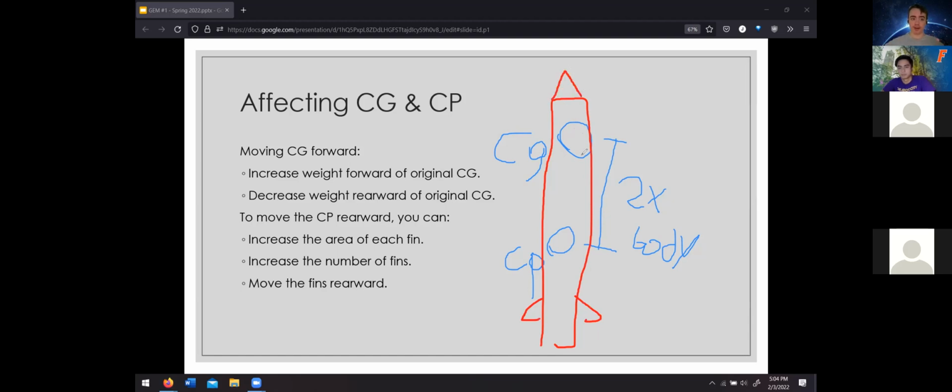So that's kind of empirical. There's no magical scientific formula for it, but generally that's something Rocketeers agree on, I guess. And if you have lower than this distance, then you will experience some instability. So if you're lower than 2 times, you'll have instability. And if you have your CG below your CP, that's catastrophic. It'll instantly flip around when you're flying it. So don't do that. That'd be very bad. Not fun to deal with either.